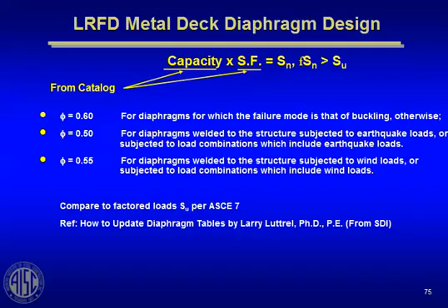Many catalogs are now coming out in terms of limit state design or LRFD design, in which case the results are given in terms of the capacity, and you've got to use a phi factor, and therefore depending on which manufacturer and who you go to, you might get different phi factors for different conditions. So be on the lookout for that.